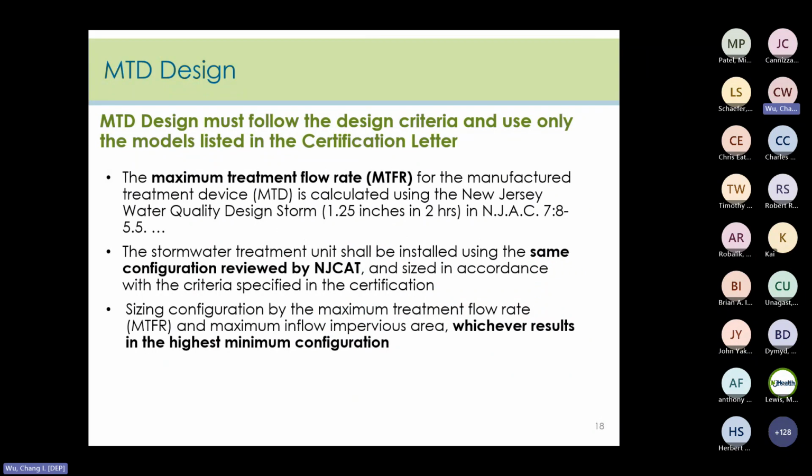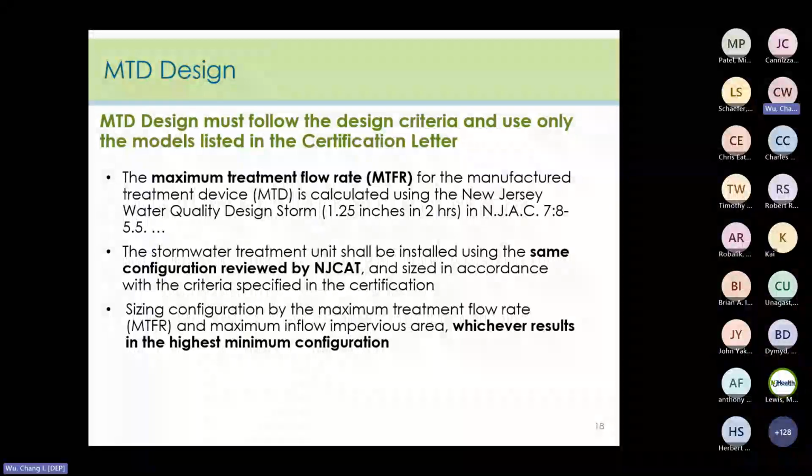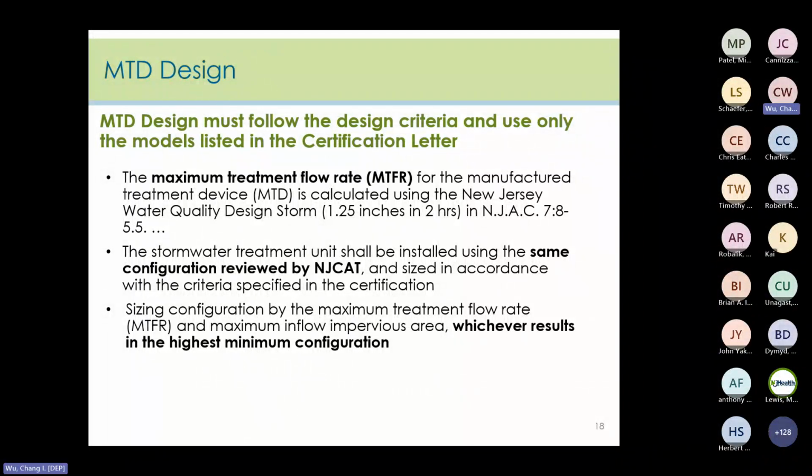And for the MTD design, we have the MTD specifically tested. So the manufacturer's other models not listed in the certification letter, even though they are the same type, cannot be used to meet the water quality design and performance standard. Also, the MTDs were tested under specific configuration and installation specifications. So an MTD that deviates from the configuration or installation specification cannot be used to meet the water quality design and performance standards.